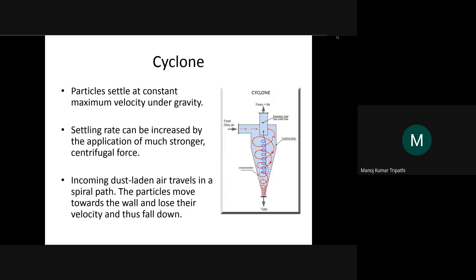Because these particles go down and they carry some fluid with them, because of the no slip boundary condition on the fluid at the solid particles, because of the continuity equation, something has to go up also. Only then will continuity be satisfied. So these particles go down and they send up the fine particles plus air. So from the top you get the clean air, and at the bottom you get these tails or the solid particles.